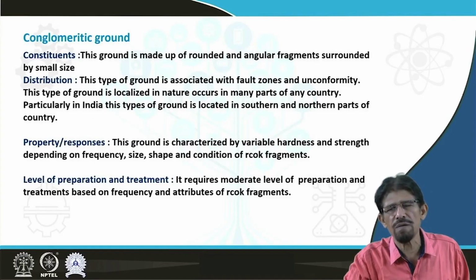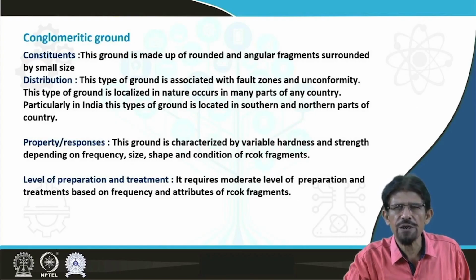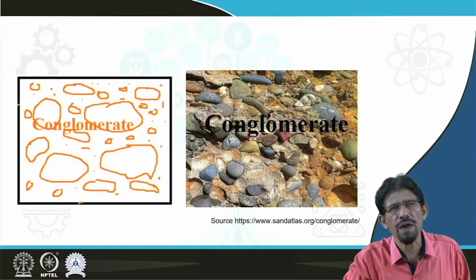This type of ground, as we know, is heterogeneous in nature. Therefore, we expect variable hardness and strength depending on the frequency, size and shape of the fragments. As far as the level of preparation and treatment is concerned, it requires a high level of preparation and a considerably high level of treatment as per the nature of this ground, in view of the frequency attributes of the rock fragments.